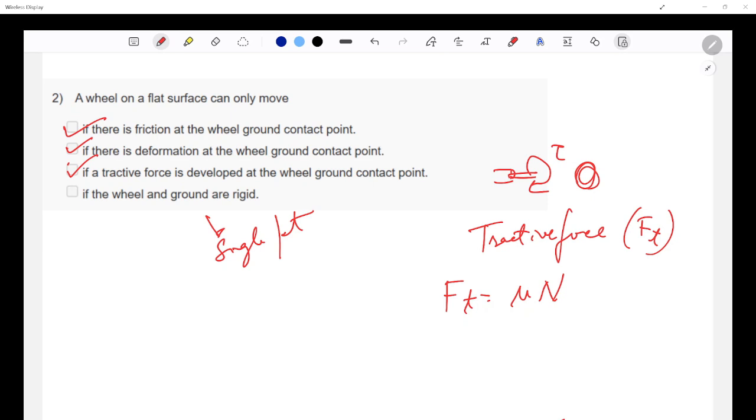Yeah. So there would be no deformation, there would be no traction generated, and the result would be that the wheel cannot move effectively. So there is no effective real force transmission. So whenever you see wheel motion or locomotion, think torque alone cannot generate motion. It needs friction, it needs tractive force, and in real systems, the deformation is essential. So a wheel moves not because it rotates, but because the ground pushes it forward.